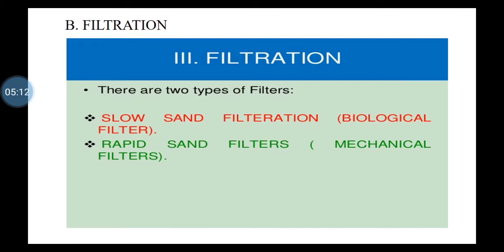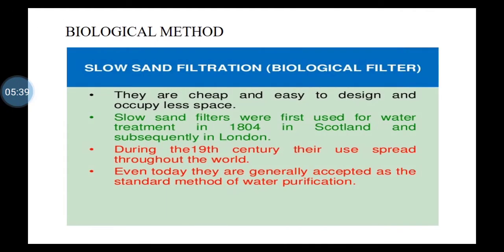The second step is filtration. During filtration, 99% of bacteria are removed. The stored water in the storage tanks is clarified water, and that is directed into these large filters.